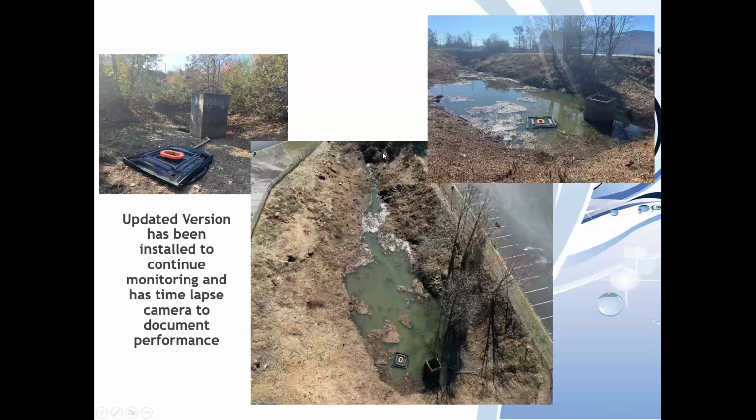This is that pond. You can see it's really steep, doesn't stay wet. It does drain out over time, but it takes a while to drain sometimes. This pond is in a commercial watershed of about 40 to 50 acres. It's older commercial development, so there's almost no other stormwater management in place, which is probably why this pond got so built up with sediment when it did. But we got it out there, got a time-lapse camera set up, and continue to monitor that.